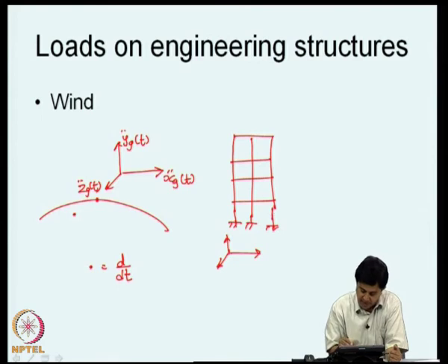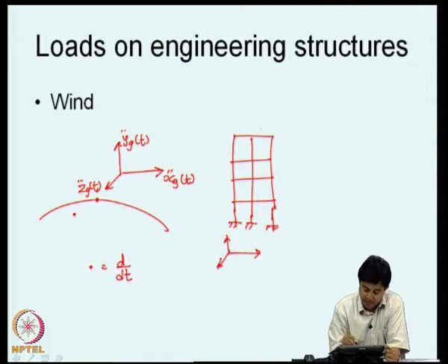Due to these accelerations, the structure will now displace, and these displacements are dependent on time. Therefore, the structure not only displaces, it also accelerates, and the inertia of the structure will oppose this acceleration, and this complex interplay between opposition to displacement through the stiffness and opposition to acceleration due to inertial properties results in the phenomenon of vibrations.